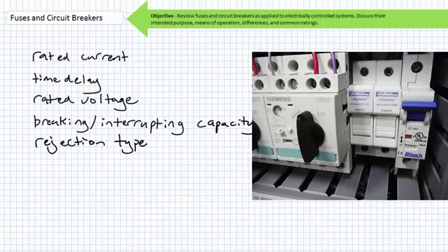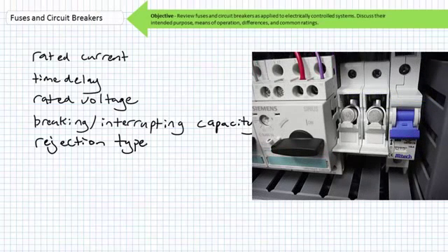Recall that even air can be considered a conductor between 2 high voltage points in close proximity. A purposely designed means of disconnection accounts for this possibility by providing a means of quickly extinguishing any arc that may form between the 2 points. As we'll learn later, circuit breakers designed for this purpose employ some pretty exotic means of doing so. Once the system is properly shut down and properly locked and tagged out, only then can the fuse holder be opened and the fuses inspected and/or replaced. In addition to following proper lockout and tagout procedures, keeping the fuses with you while you perform a maintenance procedure establishes yet another layer of protection, preventing the inadvertent startup of equipment.